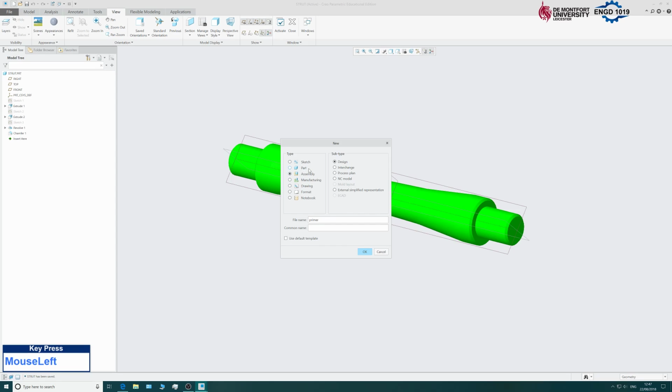So this time, rather than using a part, we're changing it to an assembly. So assemblies are where we import parts to construct our more complicated structures. Okay, so parts are individual, there's only one of them. Assemblies are where we use those parts to build up the more complex mechanism. Okay, so click OK, and again we need to change this to millimeters, and we'll click OK.